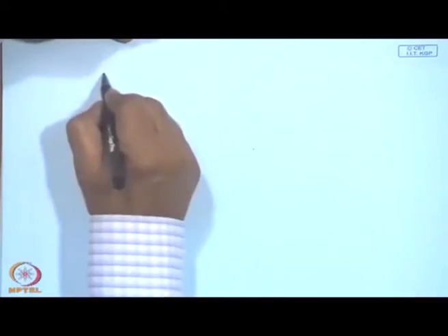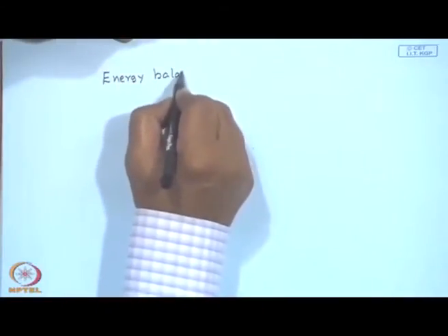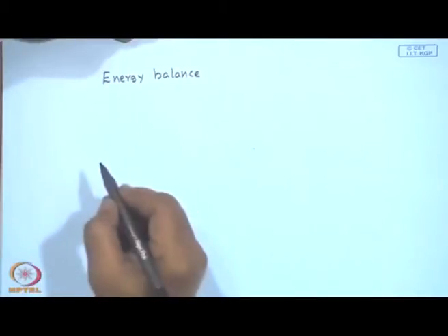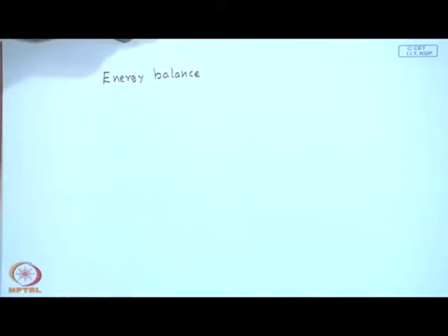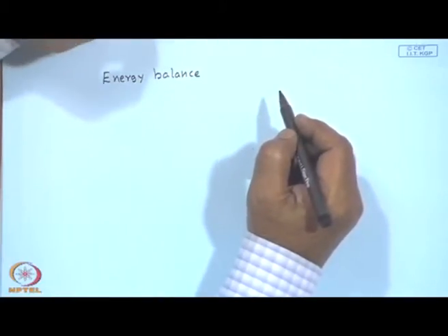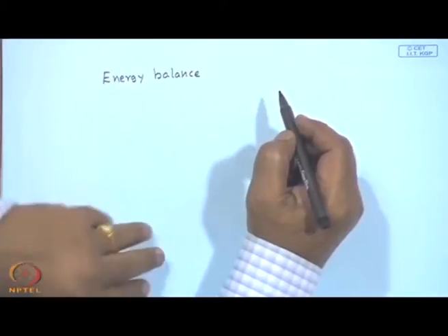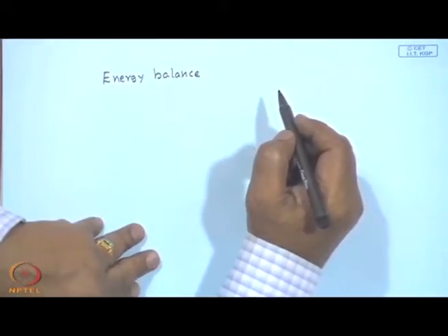Given this, before we come to the energy balance, back insulation is provided to reduce the conduction losses, and the top glass cover reduces the radiation loss plus the convection loss due to the wind that flows over the collector.